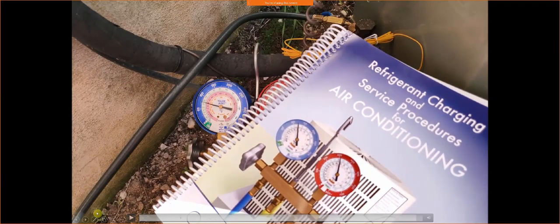So anyways, there's a subcooling example right there. He actually went ahead and found an issue where the subcooling was too high. So the charge was off, so he was going to recover. He's going to remove some of that refrigerant to dial the system in. It may not be uncommon. You get somebody out there that doesn't know what they're doing, and they decide, hey, we're going to pump up the system full of refrigerant, and they overshoot it.